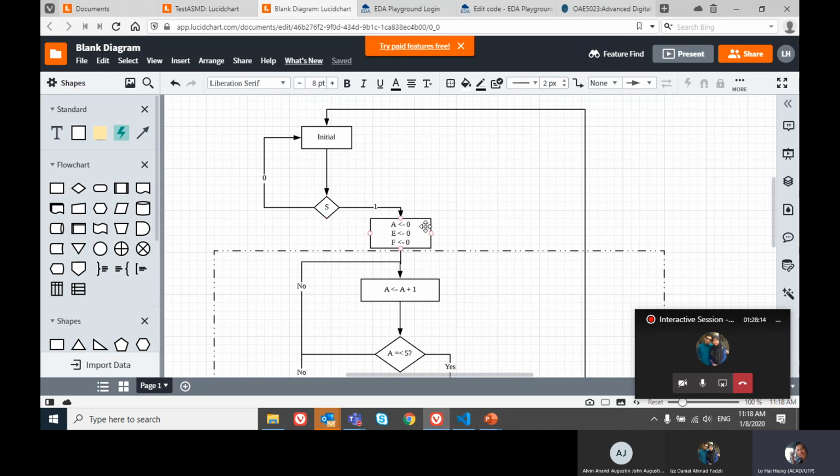I can make the design decision that I do not need an extra state. I can do this because it's following an immediate decision box. I can reduce the number of states by changing this into a conditional box. This is a simple design decision.